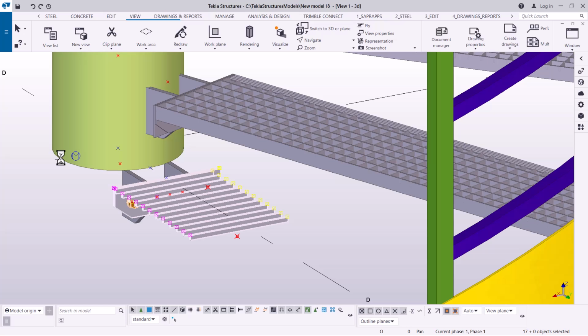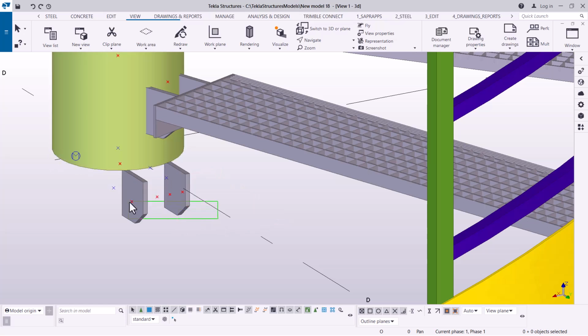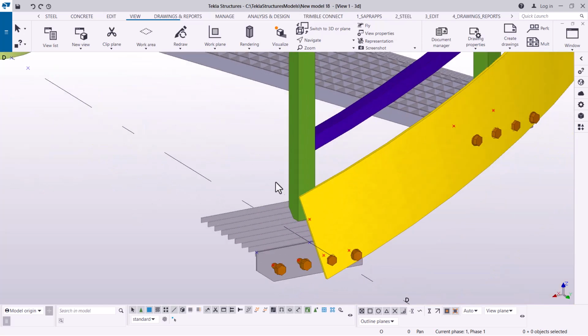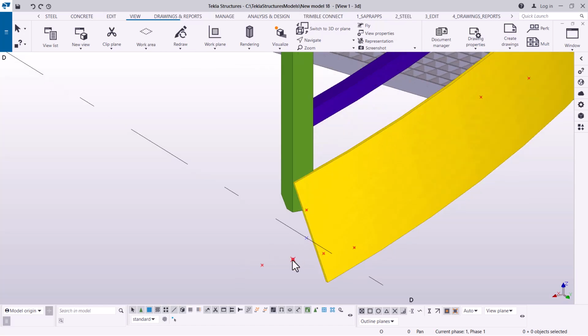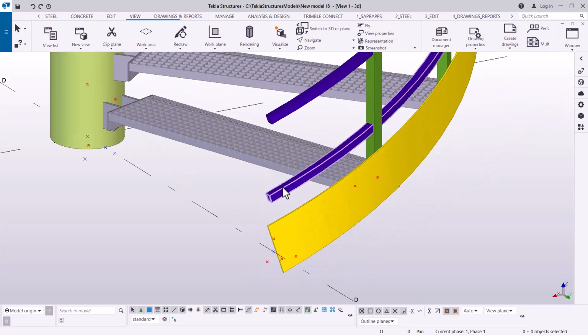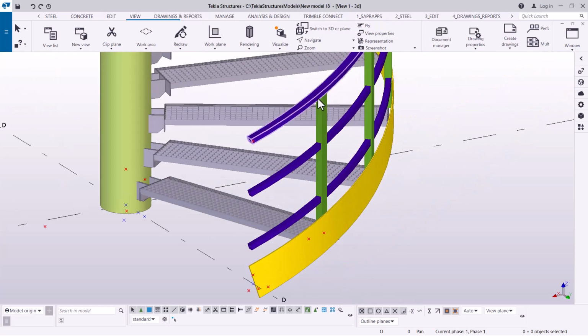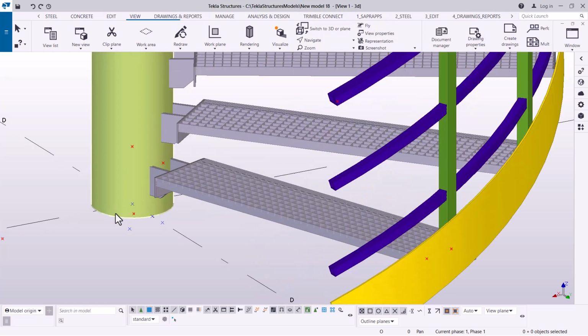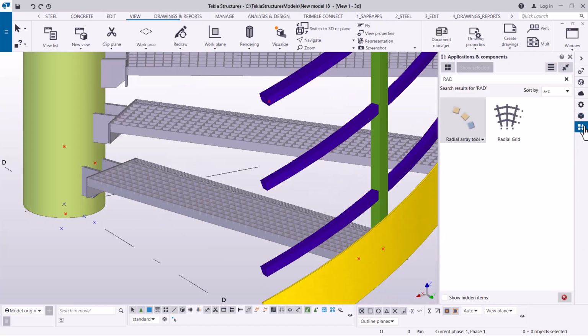because the reason why I'm deleting this, because at the bottom end here we'll place a base plate. So when you place base plate, that thread will be hitting, will even sink on the ground. So it won't make sense at all. So even this handrail, we'll just have to get rid of it. So you find this, the handrail and the post, you have to get rid of them. Now at the bottom end here, what you are going to do is to bring in a base plate. So let's handle the base plate as a different topic.